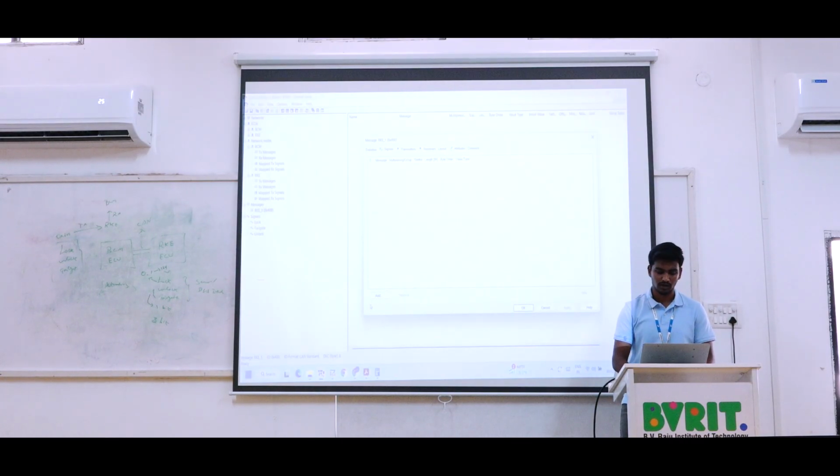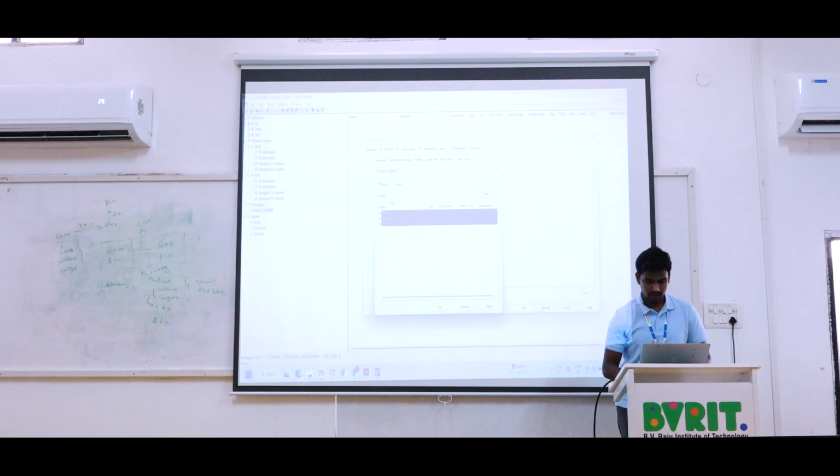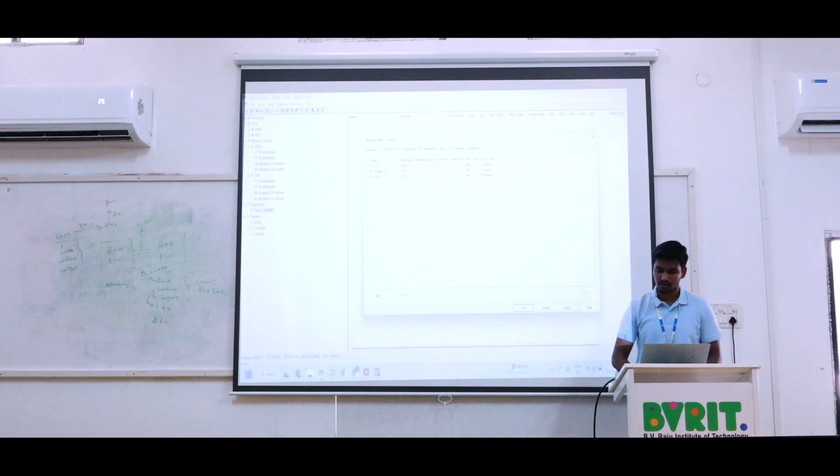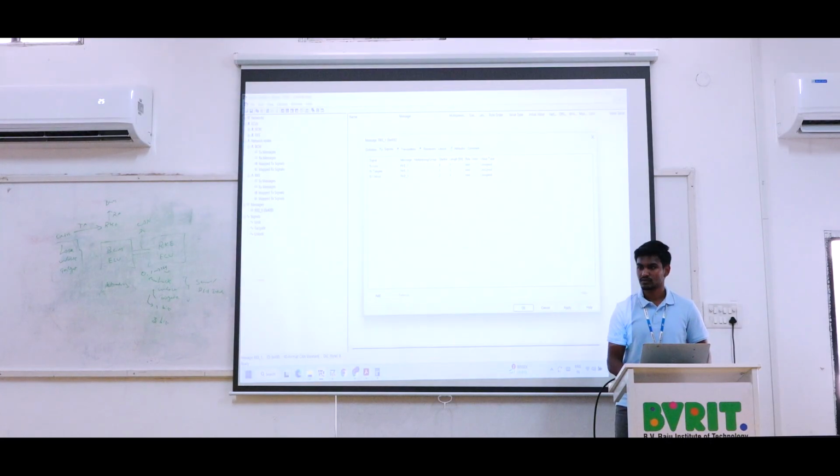At the top left or bottom you have the option as add. So you can give add. What are the signals you have created in the signal column? Everything will be shown here. Okay, here we need to add the 3 signals. I can drag all the signals, or else you can select one by one. That is not an issue. If you give OK, the signals are now showing here. So lock, tailgate, and the other one, all 3 are now mapped on this ID number 400.